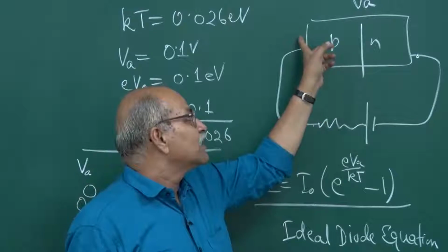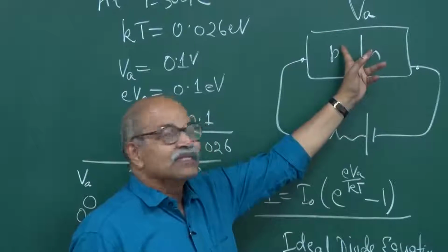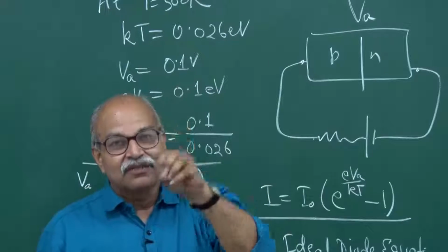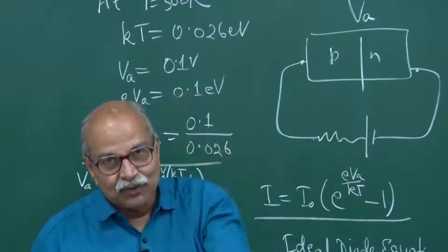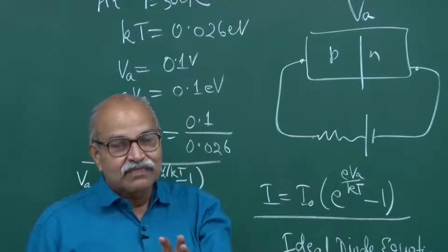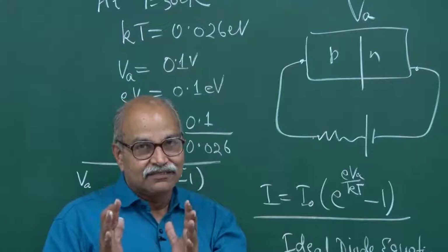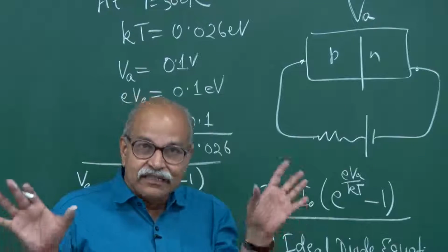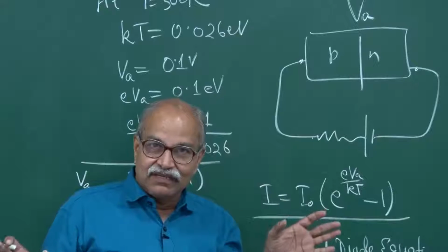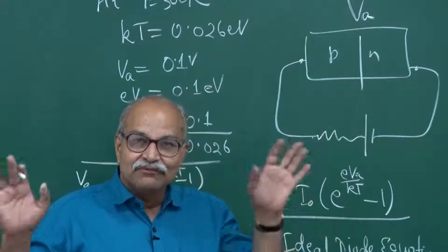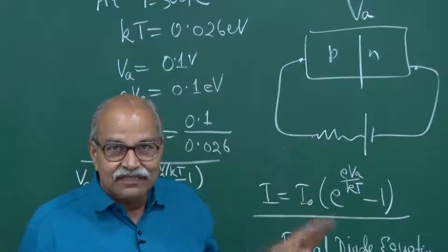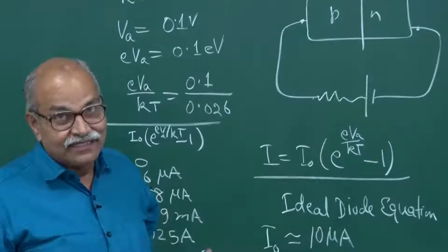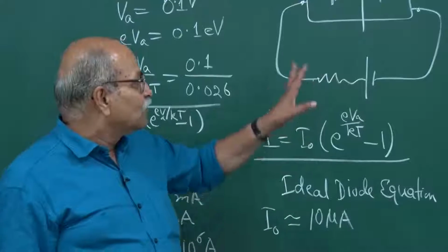Of course, the diode itself has some resistance to offer. So, whatever you apply here may not go on the junction. This depletion layer has a very small number or negligible, we take it 0, no charge carriers, but in any case that offers a very large resistance. The other regions outside depletion region where you have lot many charge carriers, that offers less resistance, and in ideal case no resistance in fact. So, all those things are there.